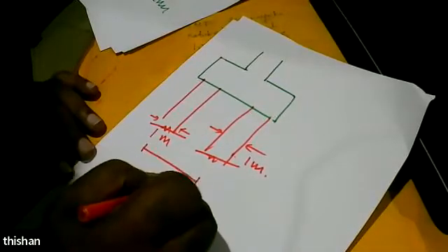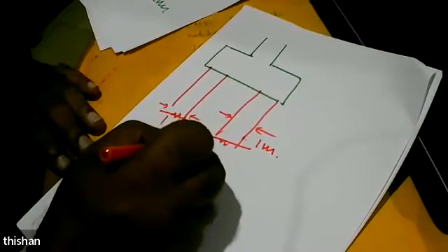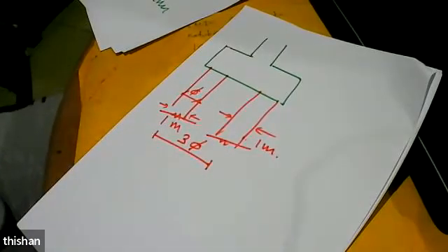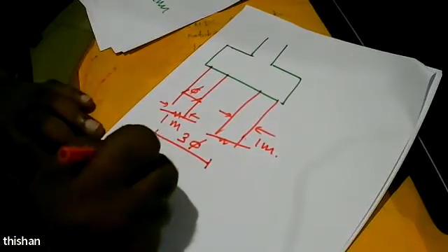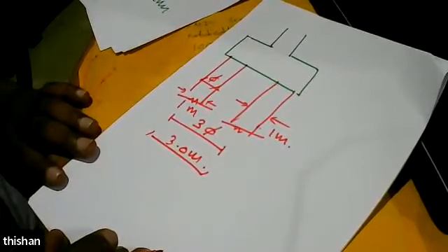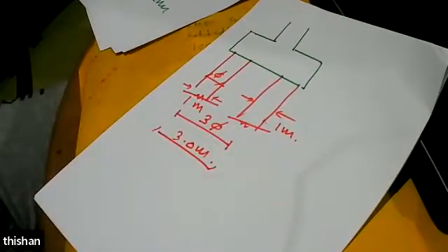Some of these rules are meant for very small piles and say 3 times diameter, center to center. So you get 2 times diameter separation between the piles. What is meant by 3 times diameter is 3 meters apart. If they are 3 meters apart, with 1 meter diameter piles, then you find that the gap is 2 meters. And here we are saying, I'm going to break the bedrock.